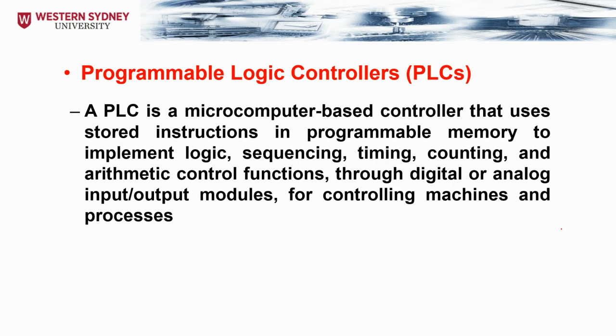Now, one of the most popular and best known process controllers is what we know as the programmable logic controller. Something like a microcomputer. It doesn't have a screen most of the time. It doesn't have a fixed keyboard, but you can always connect a keyboard and screen, or even a PC, to the PLC. A PLC is a microcomputer-based controller that uses stored instructions in a programmable memory to implement logic, sequencing, timing, counting, and arithmetic control functions through digital or analog input-output modules for controlling machines and processes.